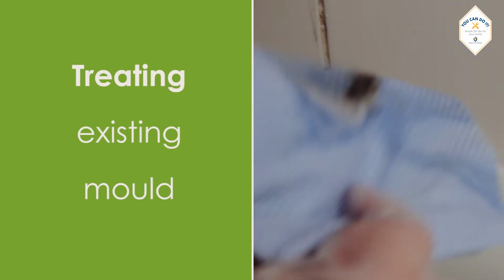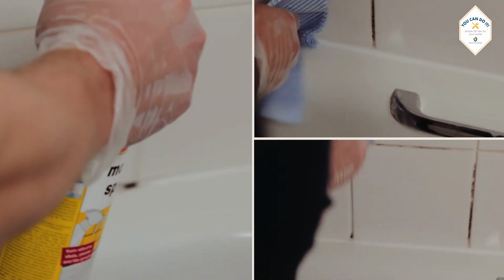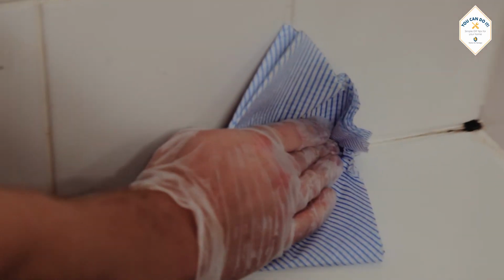Treating existing mould. Treat existing mould. Wipe down the affected surfaces using a specialist mould spray. These can be found in most supermarkets and hardware stores. Avoid using bleach and washing up liquid. Also, do not disturb mould by brushing or vacuuming, as this can increase the risk of breathing problems.